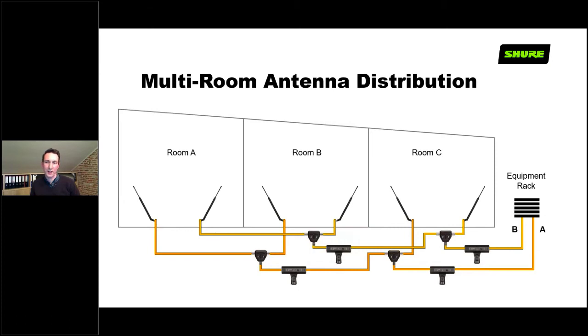And what I'd like to add as well is that when designing this, really look out that you put an A and a B antenna in each room to protect that diversity reception across the floor plan. That's really going to add to the reception quality in this system. I think you mentioned earlier, Kristof, that we weren't going to talk about multipath and wide diversity, assuming most of you are aware of that situation. But yeah, that's the point.